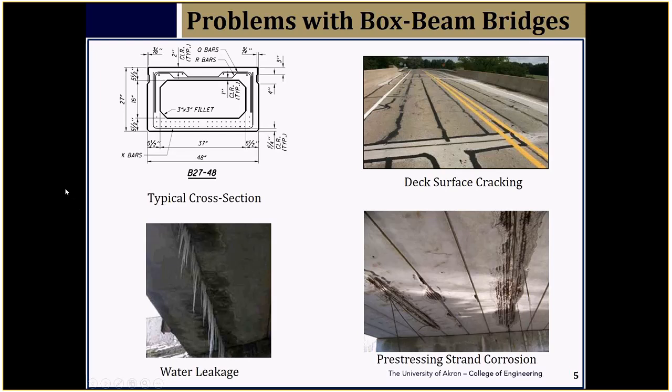And to the extent that the strands do detach and hang, it can look quite unattractive, so to speak. These boxes still maintain some amount of structural integrity, but we all know that any pre-stressed concrete is good enough only as long as the strands are intact.